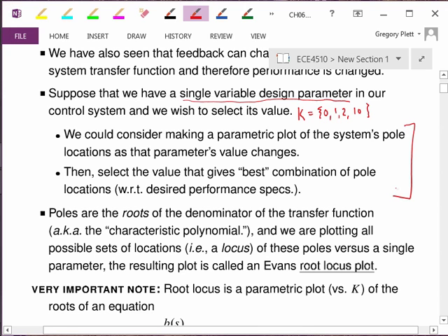After we get started, we'll look at some examples of doing things very manually, brute force, but after that, we're going to find techniques for drawing these plots of the closed-loop pole locations very quickly, with very little hand calculation, just drawing stuff on an s-plane, and that's really valuable. It's a back-of-the-napkin kind of thing. You're sitting at a restaurant with your friends, designing a controller, and you don't have MATLAB handy, so you just whip out your napkin and draw where the poles are going to go. It's going to be just like that.